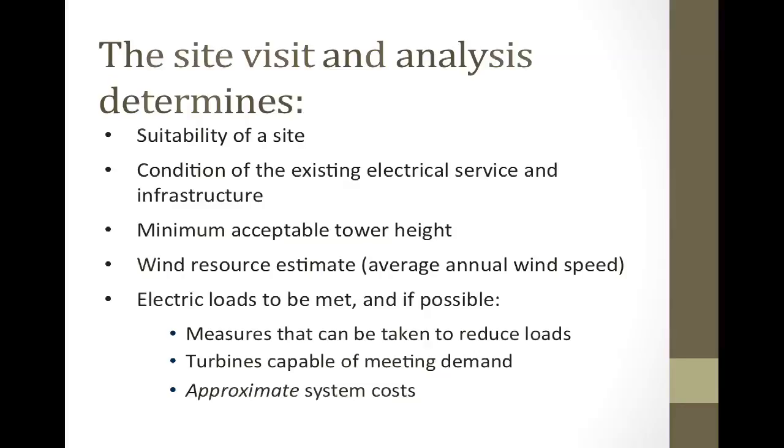We will talk about what a minimum acceptable tower height would be, and that will have a lot to do with this next bullet, what we expect the wind resource will be, and we're going to need to identify where we get that information from. There's an Energy Periscope website where we'll be looking, and a couple other sites where we're going to get good wind resources, just what we think the wind speed will be at a particular height. And there's no sense in putting a turbine on a short tower if it's not going to capture much energy. That makes about as much sense as putting solar panels in the shade to keep them cool.